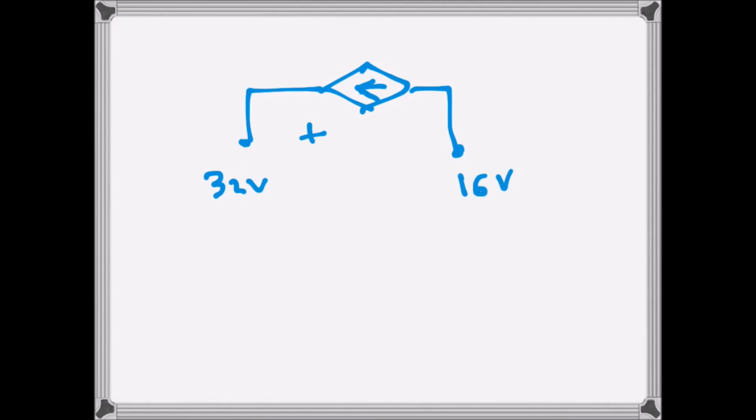That means here the voltage drop is 16 volts. And the current here is of course 3I1, that means 9 amps. For this one as well, the current is going in that direction, and in the direction where current is going, the voltage is also rising. There is a voltage gain here. There is no drop here. This is a voltage rise. That means this is also delivering power.